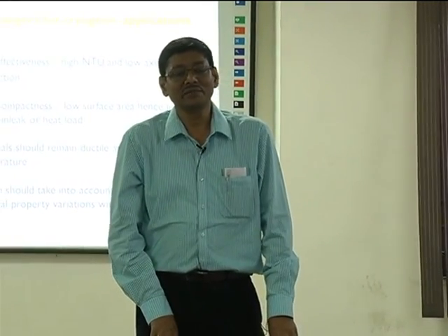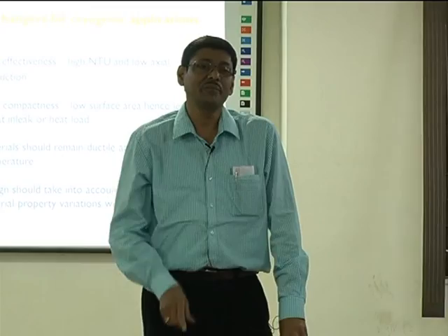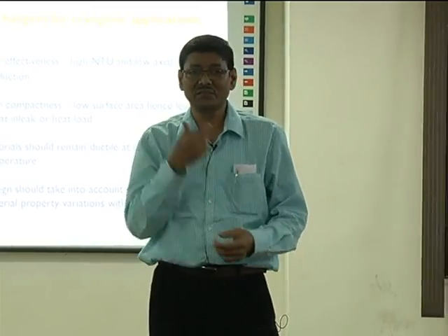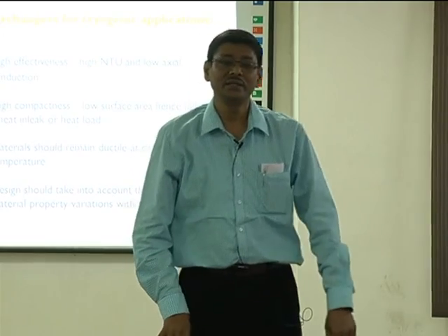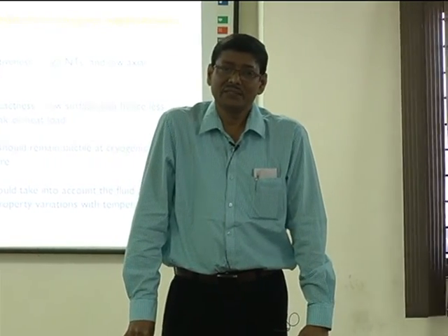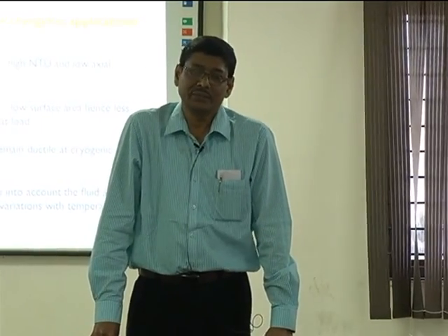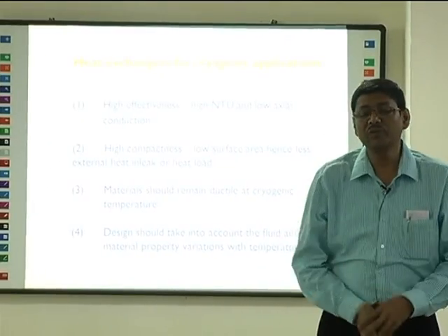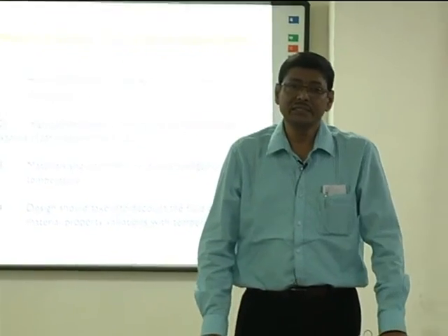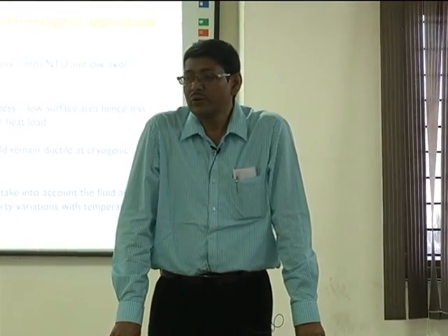Okay. For the same insulation, where K is the same value for both cases, because the surface area is large, the amount of heat that can come into this heat exchanger will be high; with smaller area it will come down. Okay, there is the point that you need compactness. But of course, compactness also gives you the space requirement advantage, which is essential in the case of flight-borne systems.